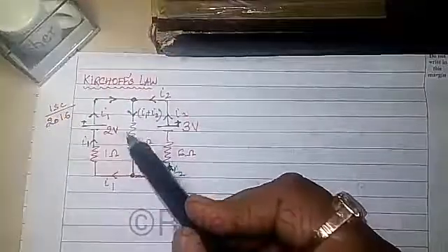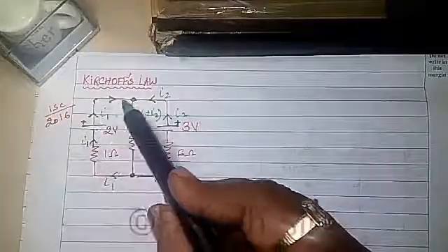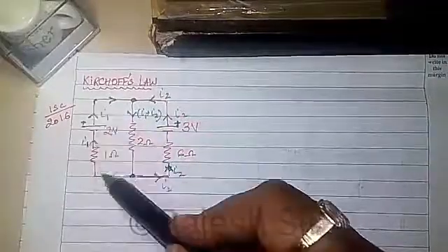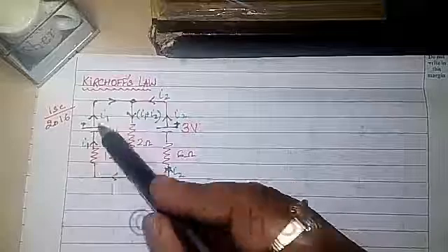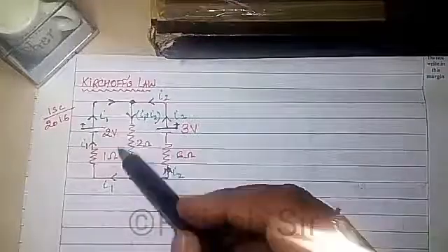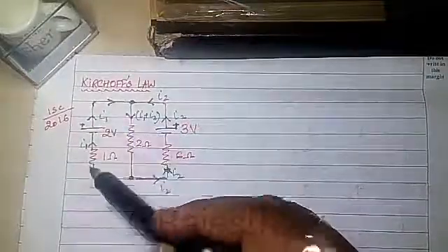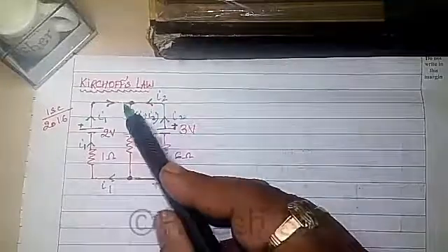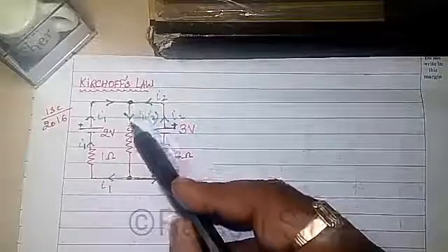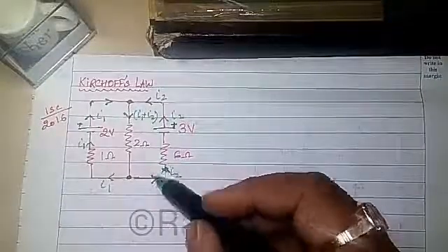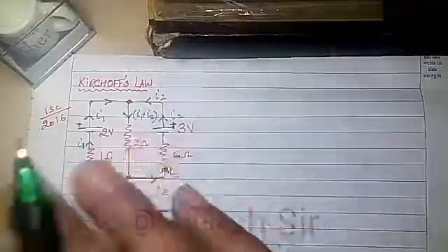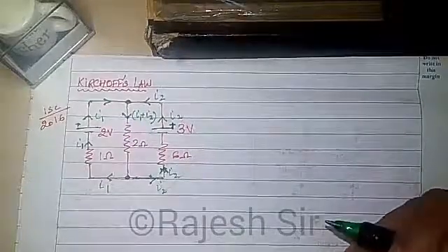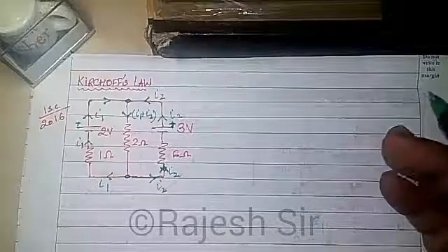Remember, a branch is as simple as a road. This is the crossing. If a certain number of charges are coming, the current continuing is the same, so the same current is going to flow in this entire branch, I1. Similarly, the same current will flow in this entire branch, I2. At this node, the two combine together and begin to flow from top to bottom, and that is I1 plus I2. That's the first step: draw the current from each battery and distribute it at the nodes.